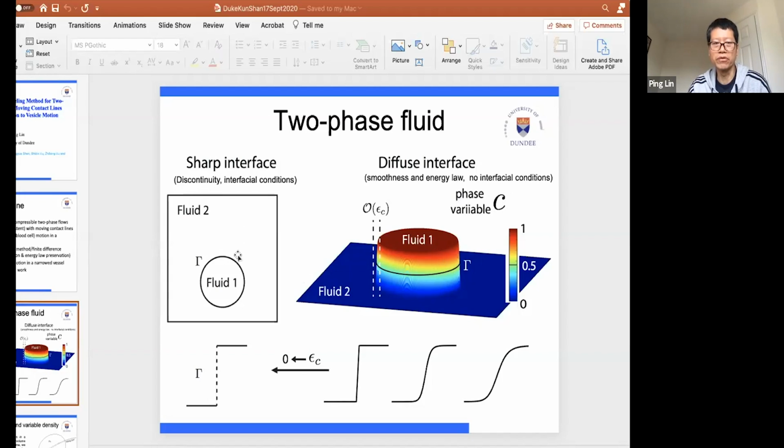In the sharp interface model, you are tracking the interface in motion. You need to catch it, right? And here you can capture the interface by drawing the level curve of C. You can get the interface, but everything you solve is a variable in the whole domain, and you don't need to worry about the interface conditions, right? Then you can apply standard PDE code to solve it.